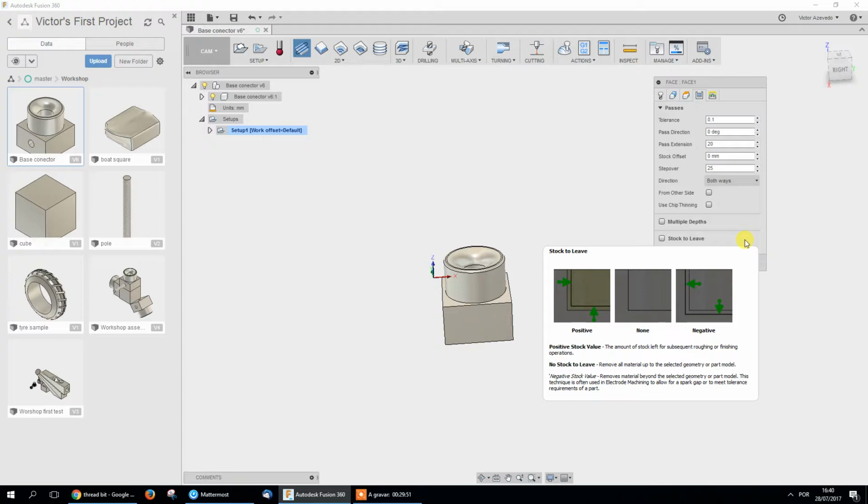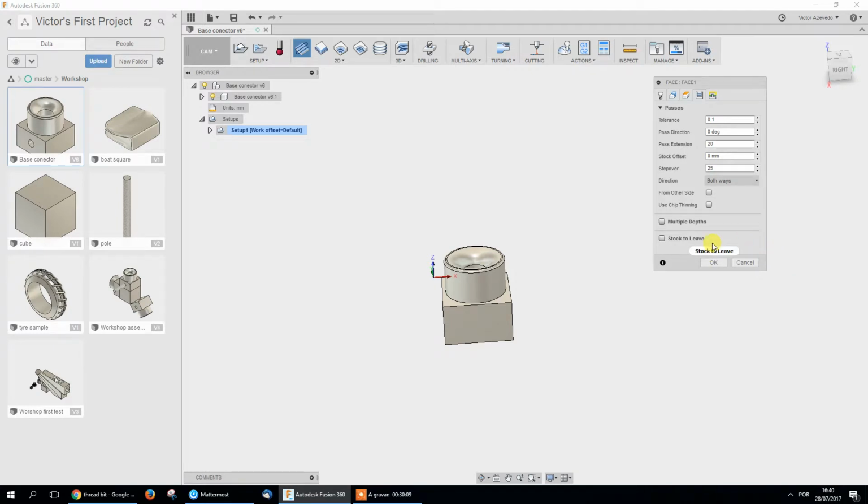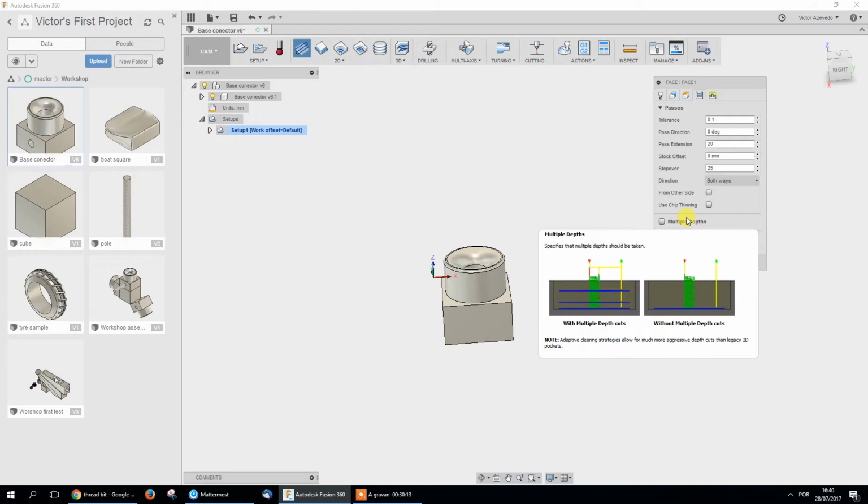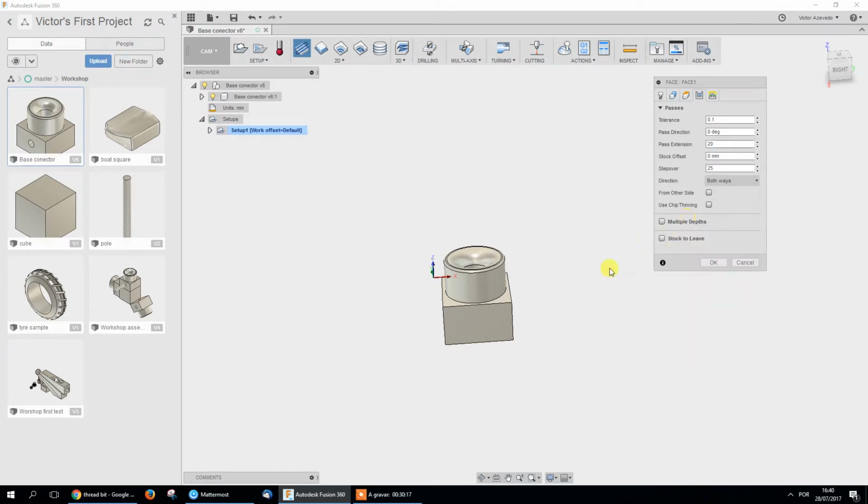That's why in the mask, I took 2 hours to remove most of the material, and then 7 hours just to remove the remaining for finishing, because I left like 0.1 millimeters in the whole mask to be removed. Okay, and the step over in that case was like 0.1 or 0.01. It was really small, that's why it takes so long, and the tolerance was really low also.